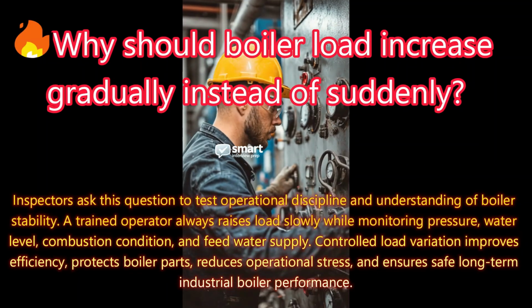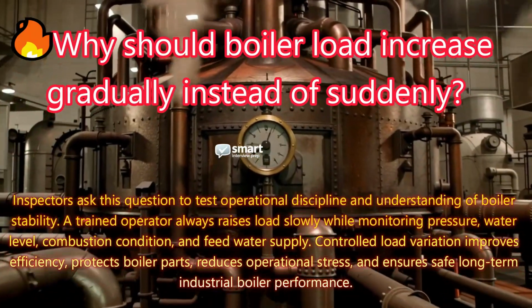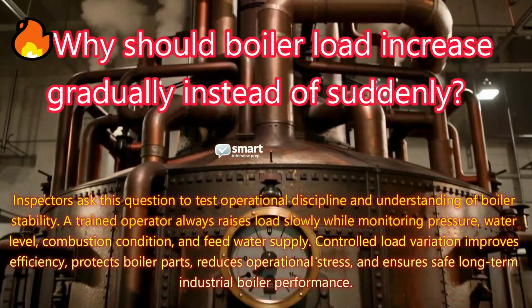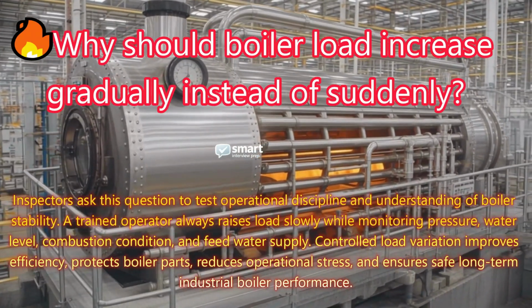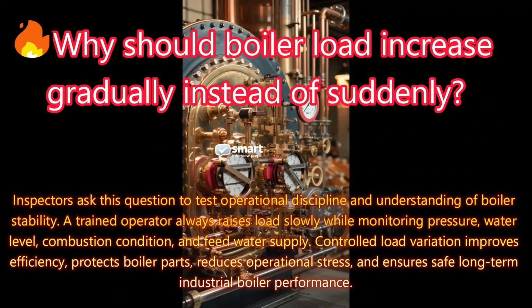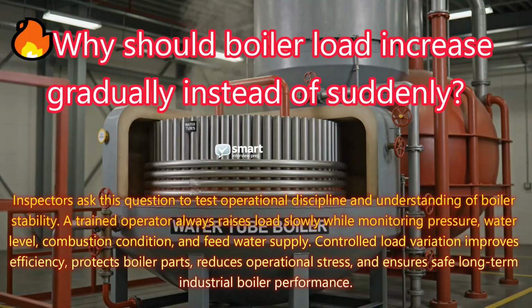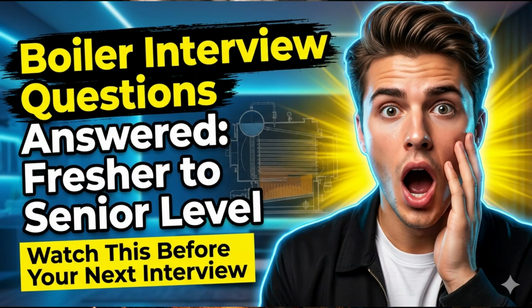Inspectors ask this question to test operational discipline and understanding of boiler stability. A trained operator always raises load slowly while monitoring pressure, water level, combustion condition, and feed water supply. Controlled load variation improves efficiency, protects boiler parts, reduces operational stress, and ensures safe long-term industrial boiler performance.